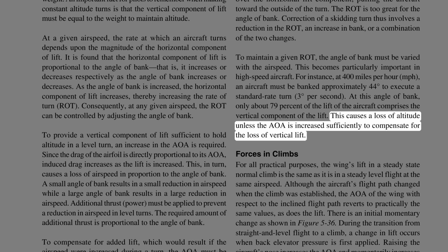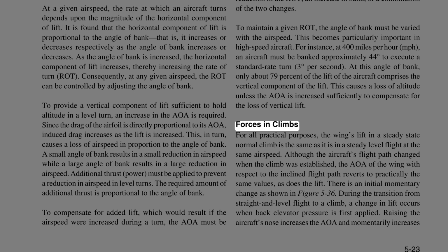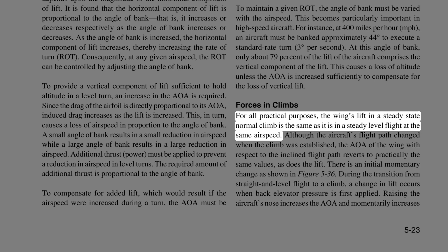This causes a loss of altitude unless the AOA is increased sufficiently to compensate for the loss of vertical lift. Forces in climbs. For all practical purposes, the wing's lift in a steady-state normal climb is the same as it is in a steady level flight at the same airspeed.